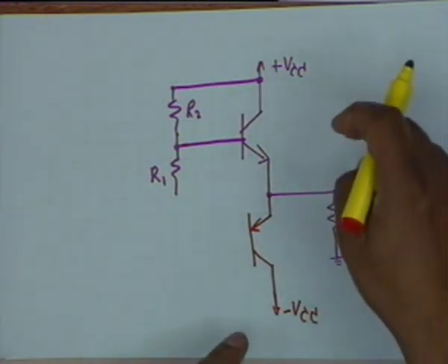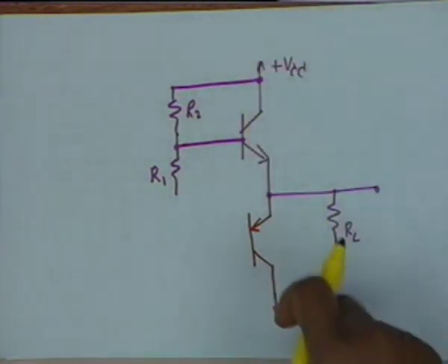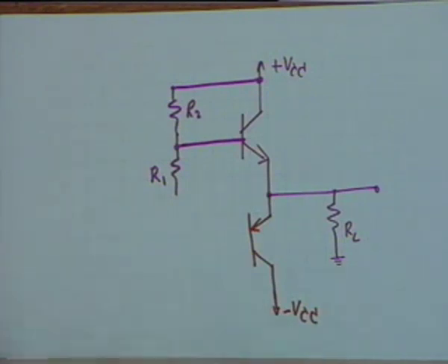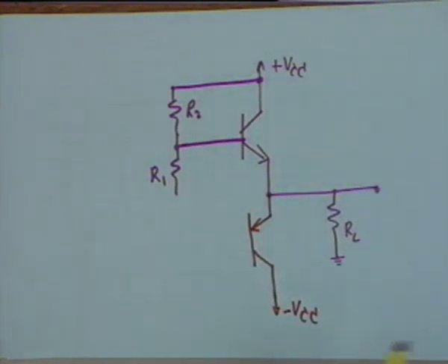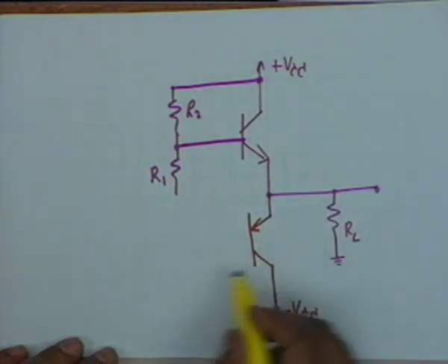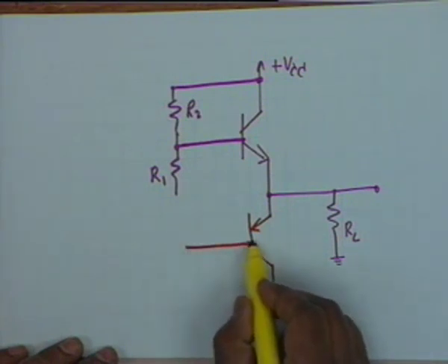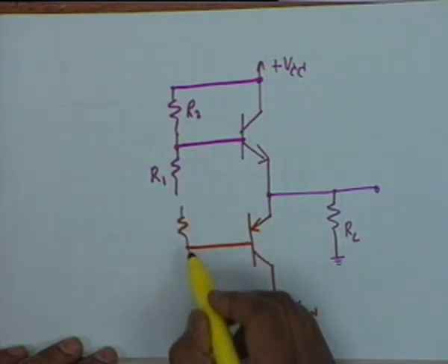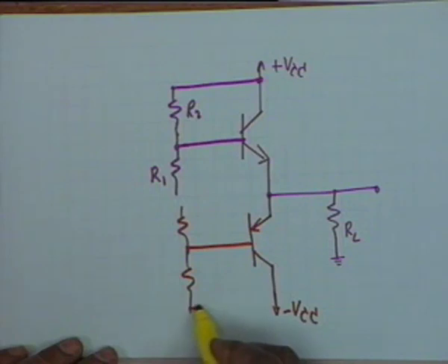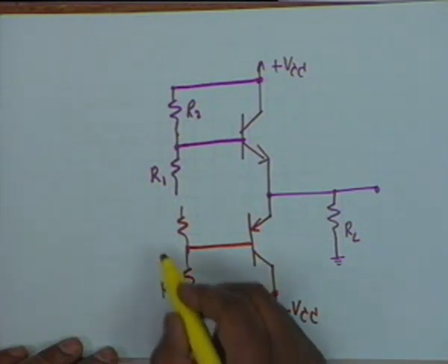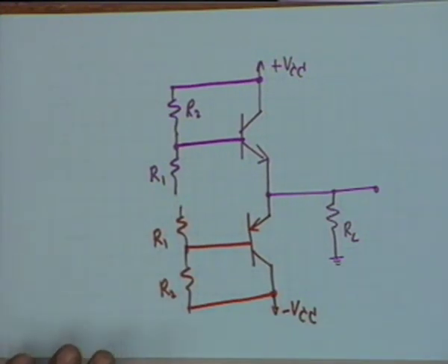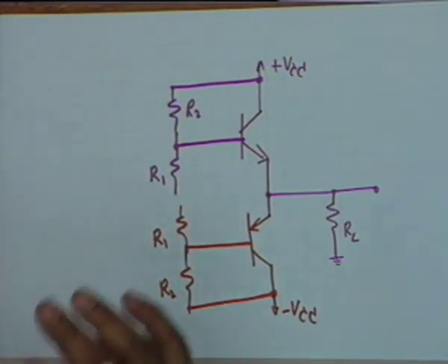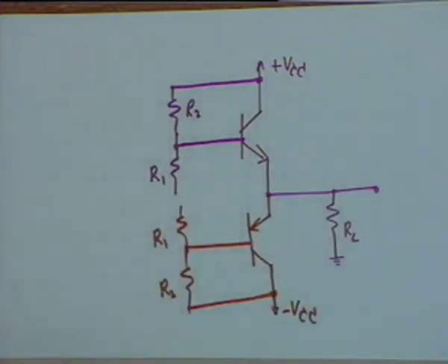You could have a single supply, this is the positive terminal and this is the negative terminal, or you could have two supplies. Alright. There are supplies available plus 12, 0, minus 12. Alright. So this is the condition, and then the usual biasing circuit. The biasing circuit is again the same, R1, R2. Obviously, in order that the push-pull circuit works, the two transistors must have identical characteristics.